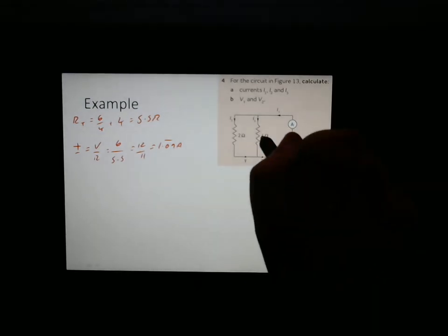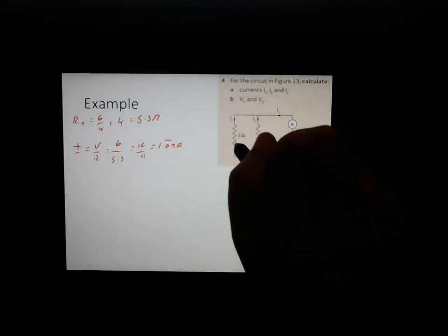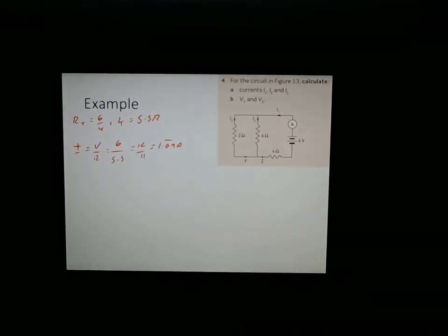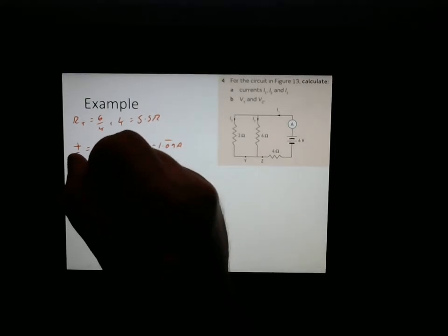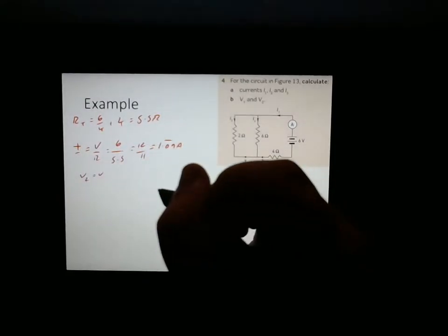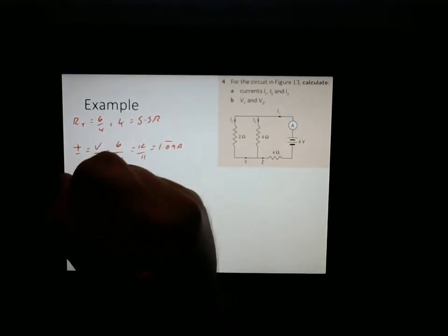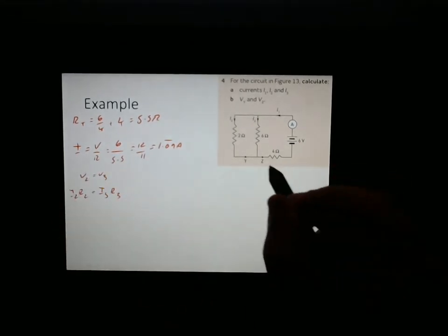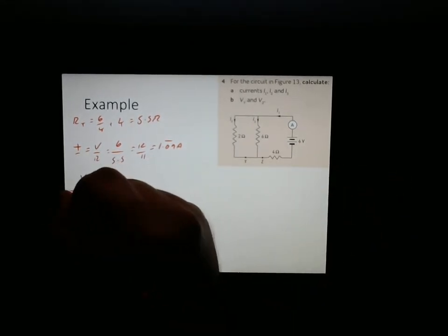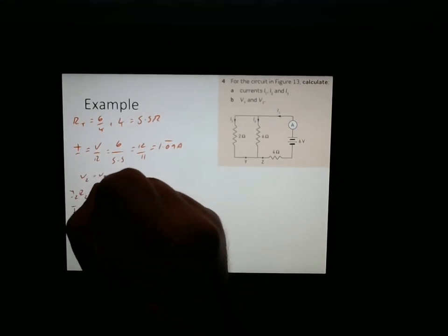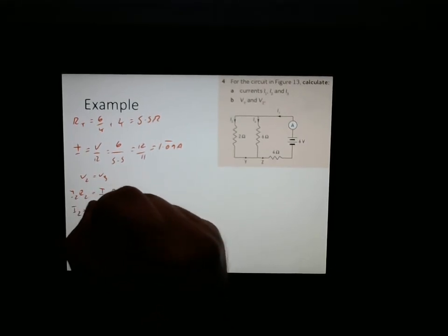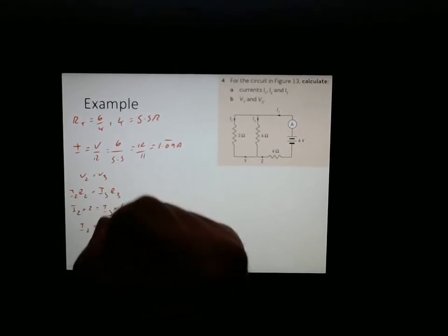And then we can go, well, what was I saying? Voltage is the same, so we'll use those two to work out that, and the fact that they have to add together to equal this one to do the same thing as last time. So, V2 equals V3, I2R2 equals I3R3, I2 is equal to unknown times 2 equals I3 times 6, so I2 equals 3 lots of I3.